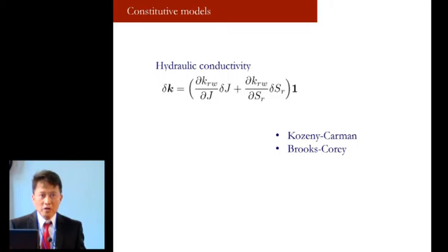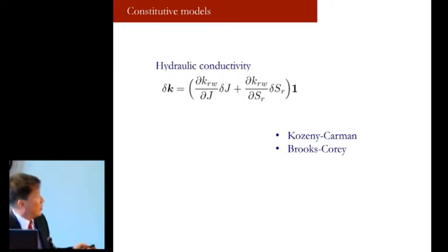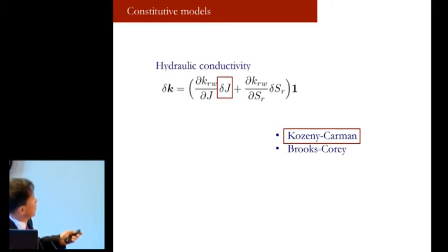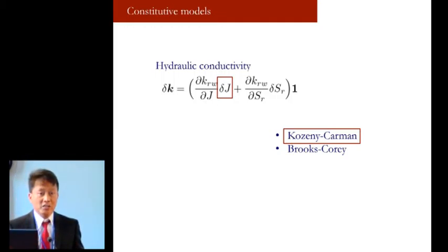Now I'm going to go to constitutive modeling and show that the hydraulic conductivity as well can be expressed in terms of the solid phase motion and the pore water pressure. So here the hydraulic conductivity is linearized in terms of J as well as the degree of saturation. This is backed up by a number of experimental observations and constitutive laws.